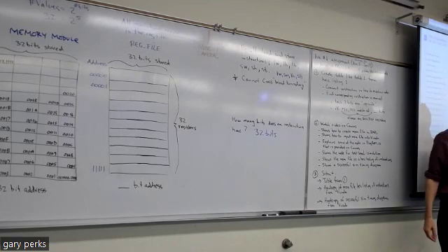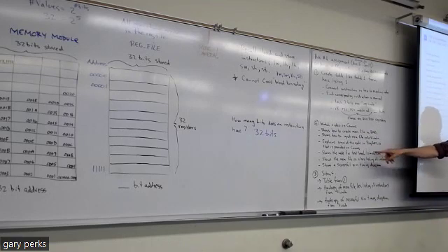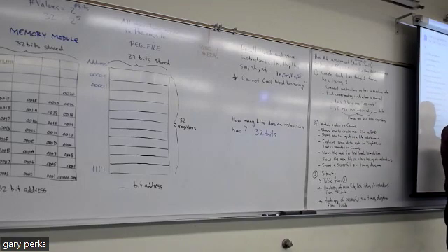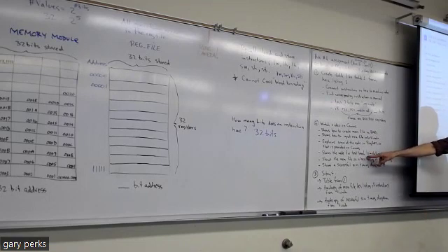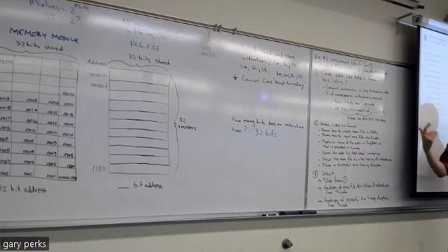Also, I explained some of the code in the program file that Dr. Hummel designed, and I show you the code to simulate it. I show you what you need for your sim file. I also show you the mem file's hex listing within Vivado, and a successful simulation timing diagram. Basically what I show you in the video is what you have to go through.